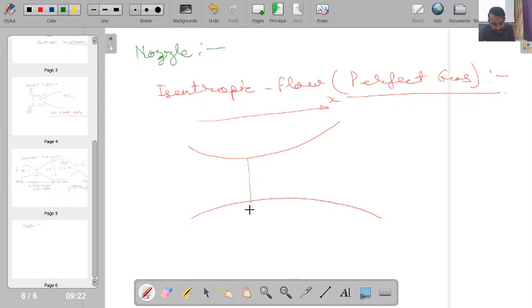So corresponding to this, my Mach number will be equal to 1. Fine. At the minimum area, I will be having nothing but a sonic situation. Now, in this sonic situation, corresponding to this, my area is say A star. Whatever area I am defining at the sonic situation, I am calling A star. Corresponding to this, my velocity is V star, and as it is a sonic situation, this V star will be equal to a star over here. Is this one clear?